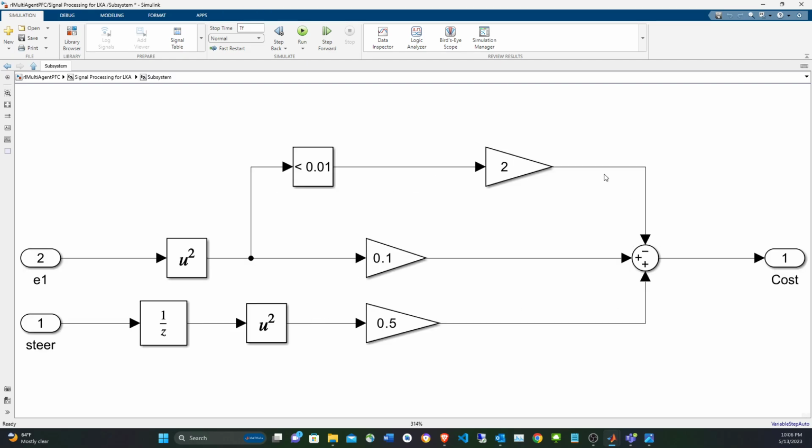So this is negative, the first one. So this is gonna be a reward, and the reward is gonna happen when the lateral deviation is almost 0. That means that your car is in the lane. So you get some reward, though not as big as the penalty that you get for getting out of the lane. And for a higher lateral deviation, you get a small penalty. So as you are deviating from the lane, you continuously increase the penalty until you get out of the lane, and you get an even worse penalty.